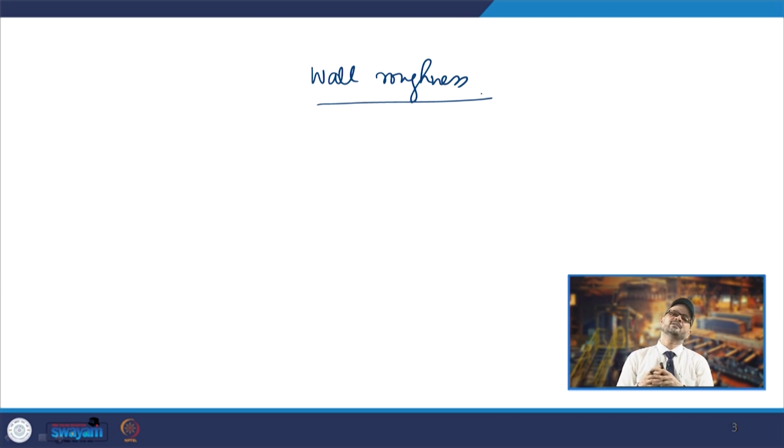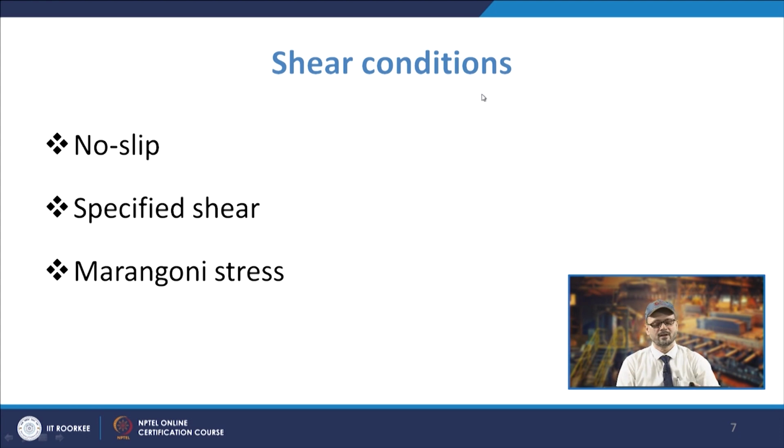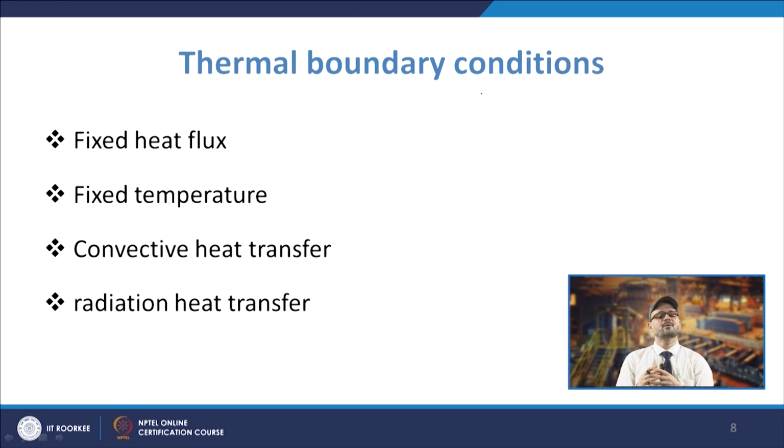Then you have the temperature boundary conditions as we were discussing. So, you will have the thermal boundary conditions. The thermal boundary conditions are important because while dealing with them, you need to know what proper condition should be selected. Like you may go for the fixed temperature kind of condition, where you say that the walls are at a fixed temperature, because the fluid is there inside the domain. So, the heat transfer will take place, since the temperature of the fluid is generally higher than the wall, and walls are normally at room temperature or at some specified temperature.